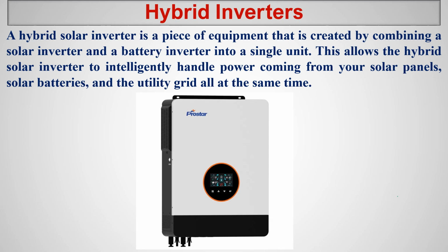For example, if you want to charge the battery using half of the energy from the solar PV and half from the grid, it's possible using a hybrid inverter. You can tune it: take 40% from here, 60% from here. You can program the inverter to make whatever performance you want.